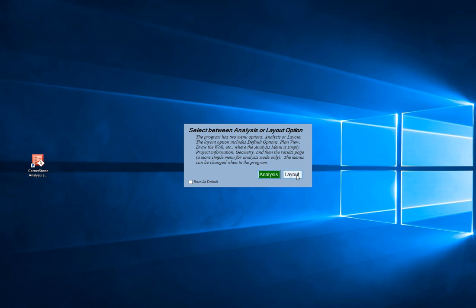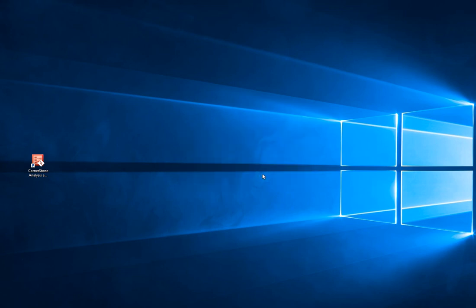So you've got a wall that's 100 feet long. It varies from 5 to 15 feet. It's going to give you a total block count. It's going through and designing each section of the wall to give you grid layout, grid count, and it produces an AutoCAD drawing ready to go to construction that you can update. But today, let's look at the analysis side of the program.